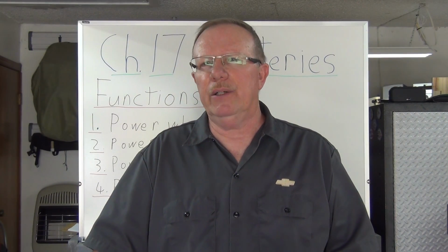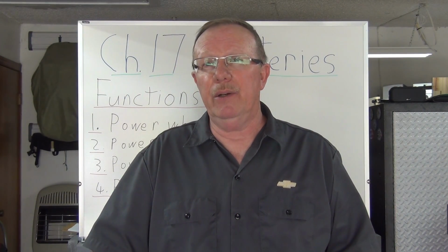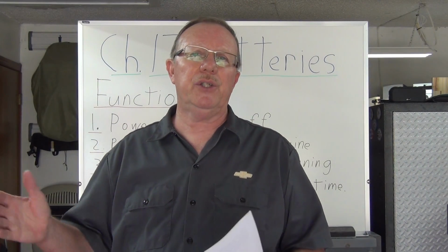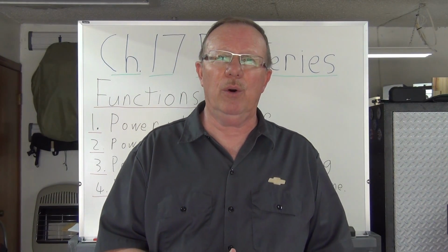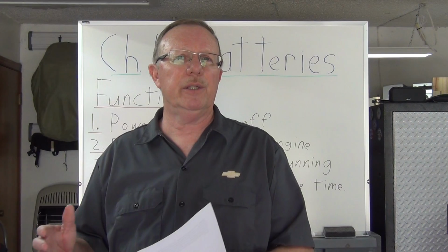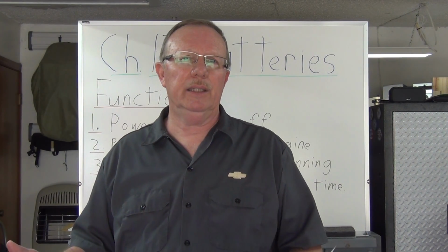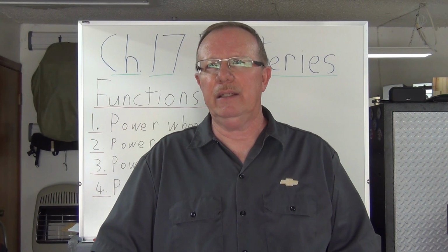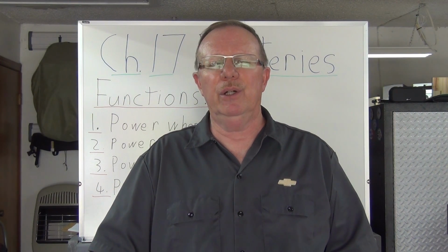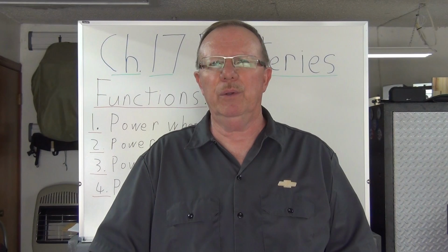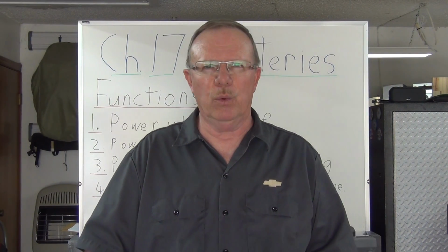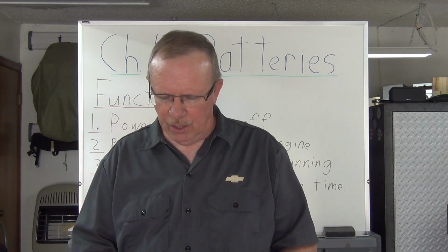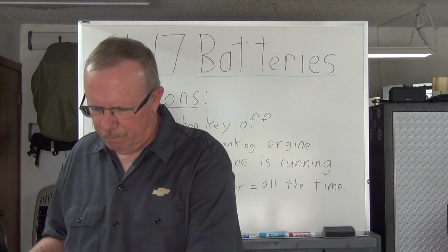But they make batteries that are deep cycle batteries that are made to be discharged all the way down because there's no alternator in the system, and then charged back up with a charger, like a trolling motor battery or something like that. Automotive batteries are not like that, okay? And so you don't want to get a deep cycle battery for your car. It won't help you in any way. That's not how it's designed to work, okay? All right, so moving on.